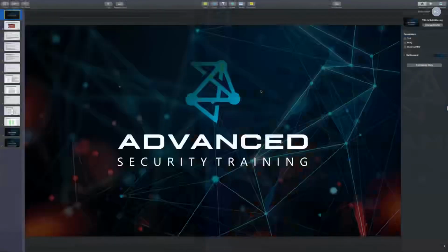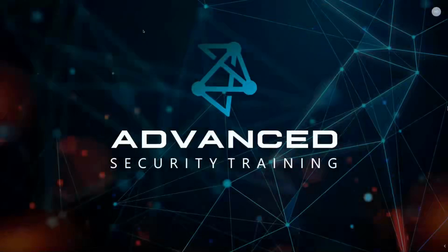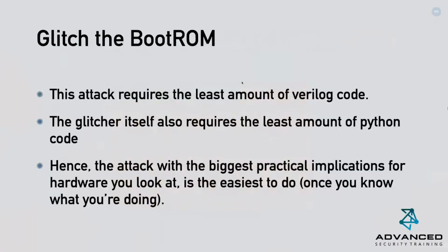All right, so let's just take a quick look. I'm going to switch to Keynote. Basically, this is our board right here that we're going to take a look at. And like Thomas already explained, what we actually want to do is glitch the boot ROM. With something like Ghidra, we can analyze and find vulnerabilities in this boot ROM. Like Thomas said, it turns out on this specific microcontroller, it only checks the value one time during boot, and so that means that it's very easy to trigger.